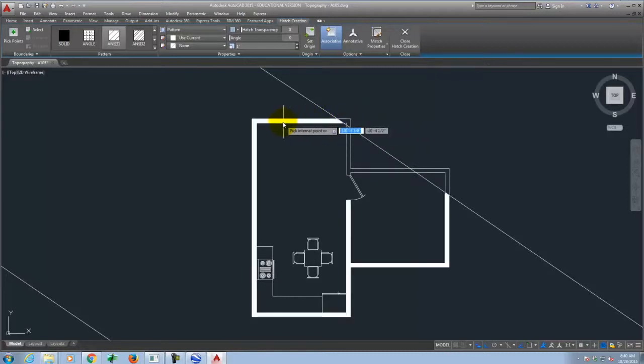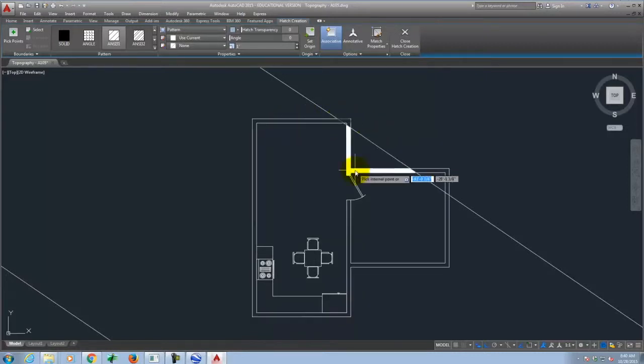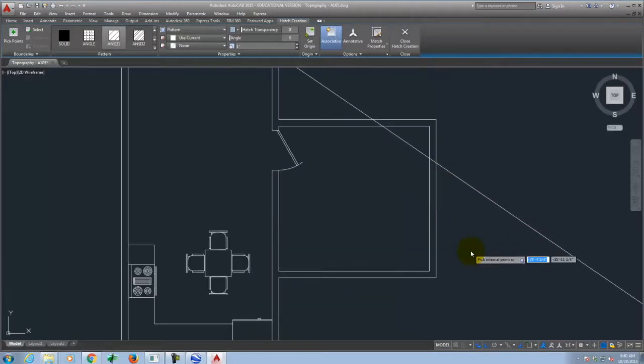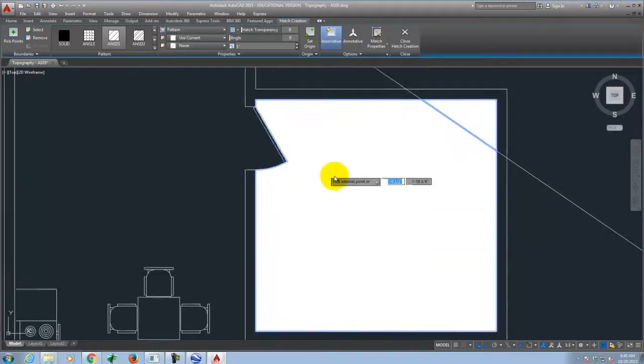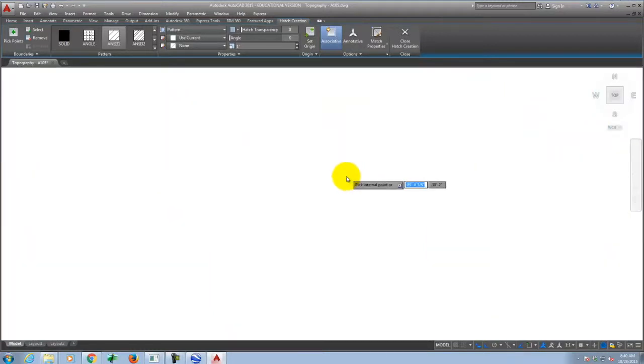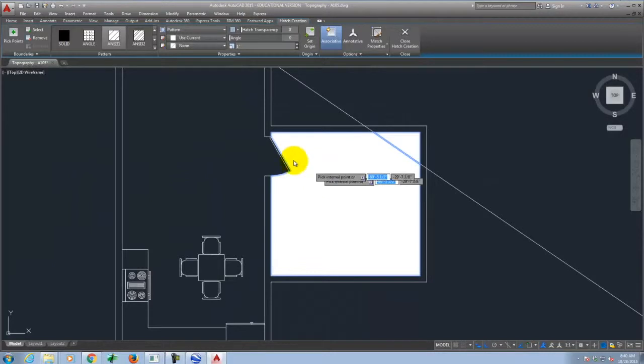So I have some options. I could fill in the walls, for example. I could fill in the floors. Right? Either way. So I'm going to pick the bedroom for right now as an example piece. Right? And I'll go ahead and I'll click. And then I'll also click here so that it's filled in the bedroom floor. If I zoom in on this, now it's not going to show up on the projector. The hatch pattern that I have is this diagonal set of lines.